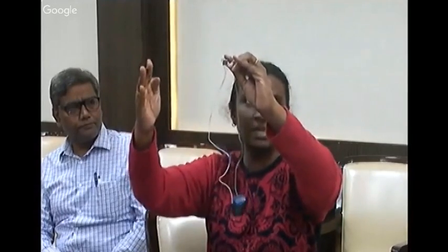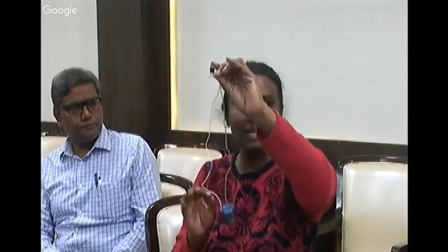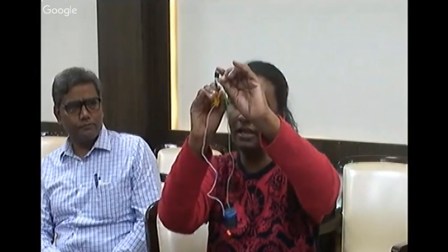Now what I have to do, this right end terminal is my gate. I have to give a gate pulse to it. Once I give the gate pulse, this will turn on. Even if I remove the gate pulse, it has to conduct. So now, in order to give a gate pulse, I'm just taking a screwdriver. I'm just going to short my anode and gate. So a little current will go and then I'll remove it. In order to short it, I'm just connecting these two.